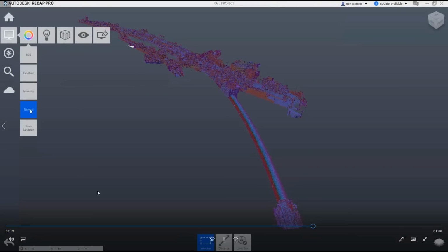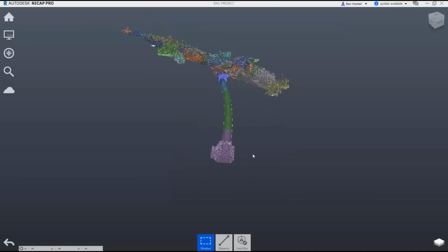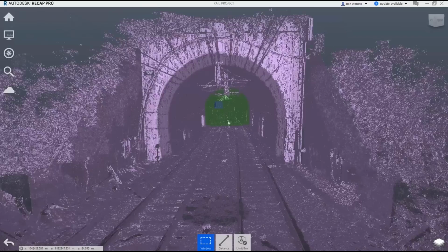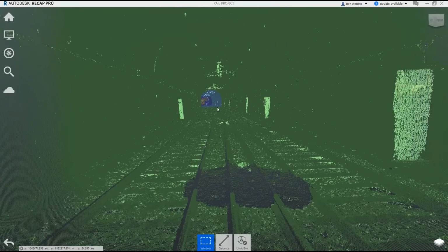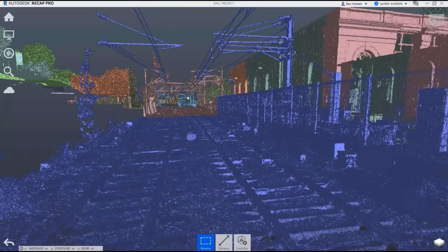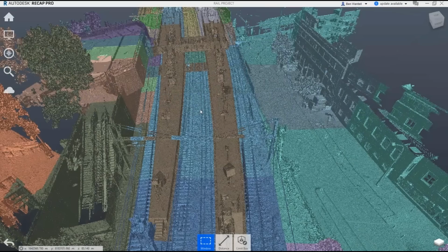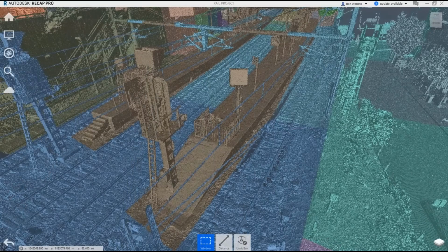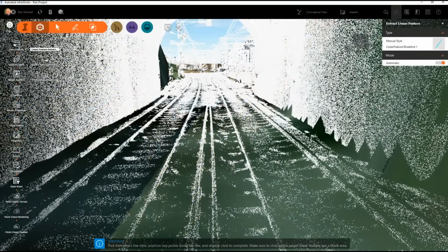that point cloud that I talked about previously. This is a fairly complex model, and this is showing ReCap. This is just showing how we can view some of those points that we bring in. We typically have an LAS file, mobile LiDAR, something like that. We can bring in a point cloud for that. And in InfraWorks, once we've got this set up, we can consolidate this data in ReCap and bring that directly into InfraWorks. And InfraWorks has a pretty cool feature called linear feature extraction.